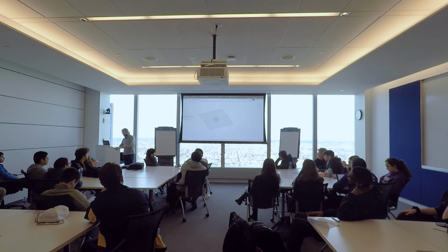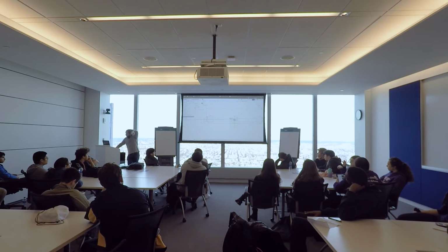I always start out with a side layout because that's how you can define how your robot sits directly on the floor. The way I define a center drop is this line here is on the center of the main drive rail. So this is obviously a piece of 2x1 drive rail. There's the 1 inch. There's the 2 inch.